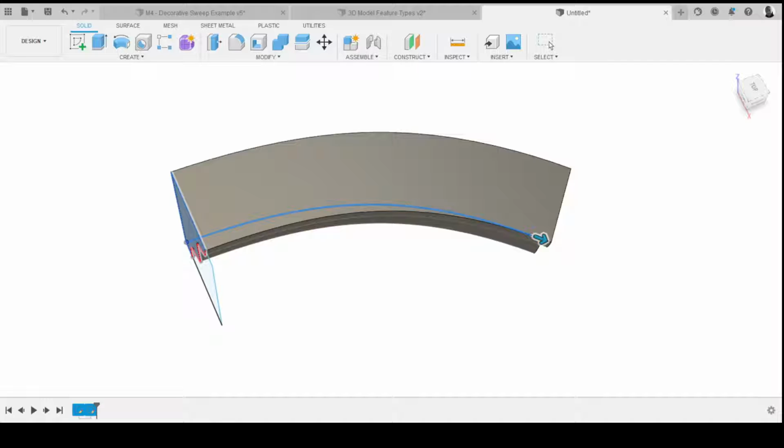If I change mine back to perpendicular, I get unable to create a valid body because the lateral edge starts off the profile in the opposite direction of the sweep direction. I do wish they'd make the error messages a bit less, you know, cryptic, frankly. So does that mean I put the sketch on the wrong side, or?